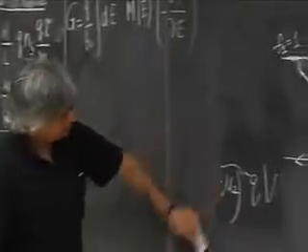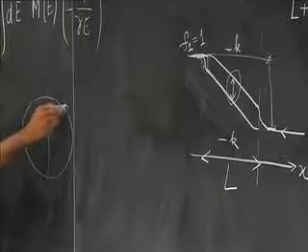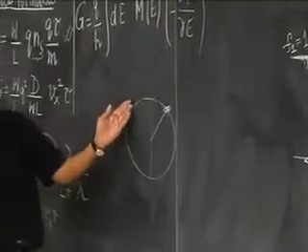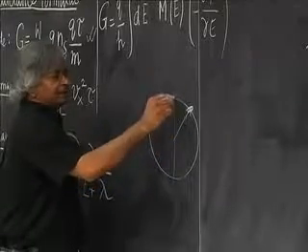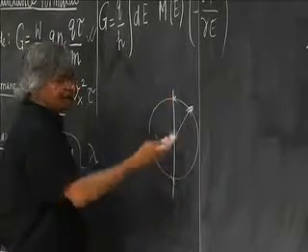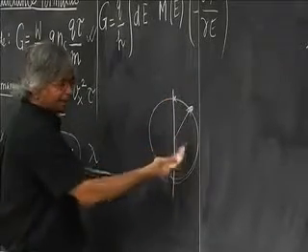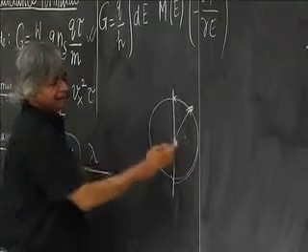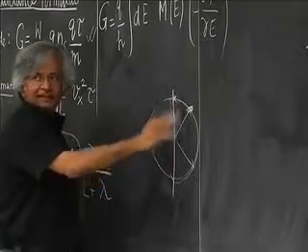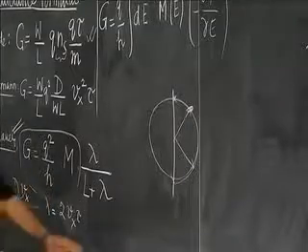And if you assume that the scattering is isotropic, so supposing you have an electron going in some direction, mean free time tells you the time after which it's scattered. But then if it's isotropic, you see, there are chances of getting back scattered. What I mean is all of these are like northbound lanes. The current is reduced, of course, only if you get scattered into a southbound lane. As long as you're scattered somewhere here, it really doesn't matter. So it's like only as if half the scatterings matter, which is why you usually put in this 2. That's it. Okay.